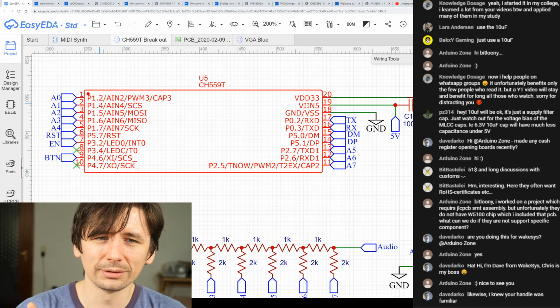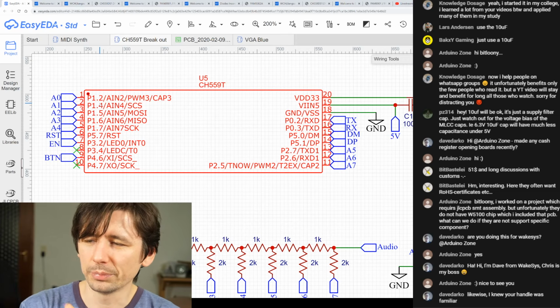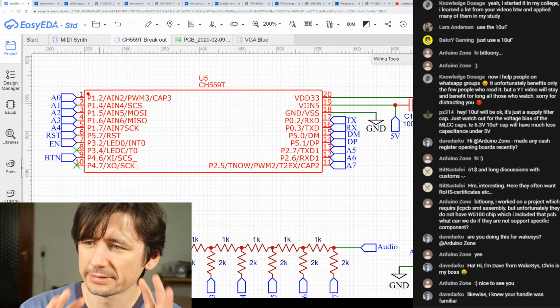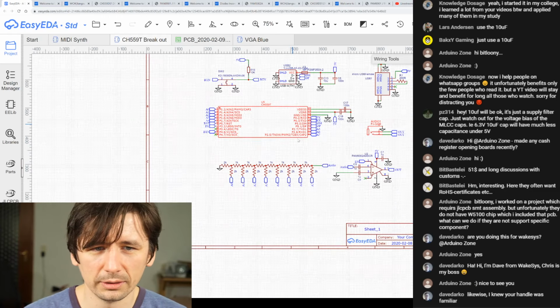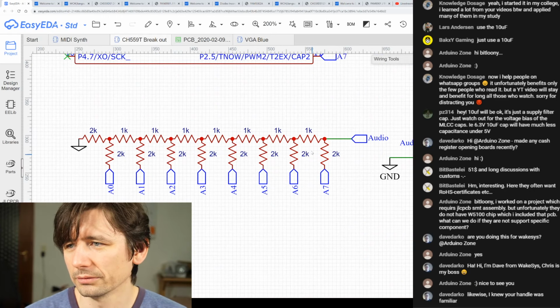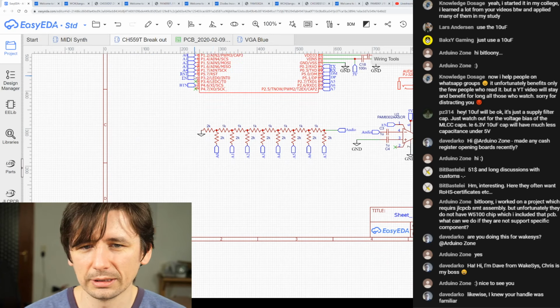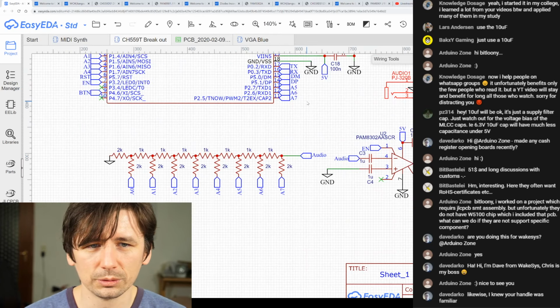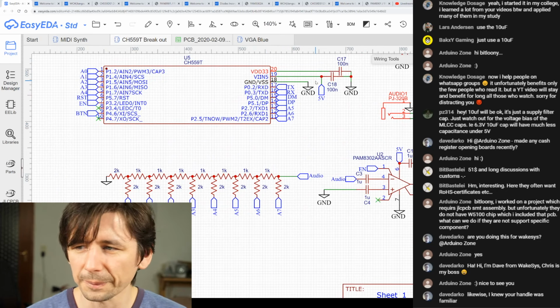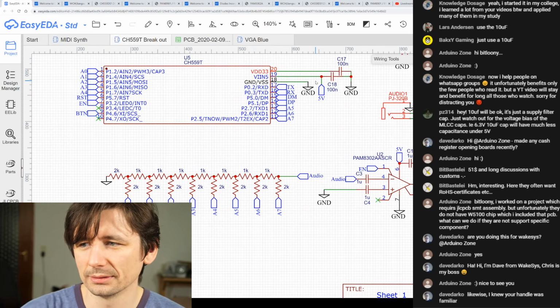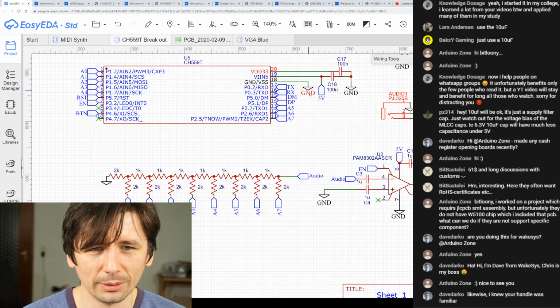That's inconvenient. So I have to shift around a few bits. But I think with 2 write operations to the I/O, I can quickly set the sample. So this is simply a digital to analog converter, a simple one with the resistor ladders. And I can write with two writes to some registers. I could set the voltage level of the current sample.